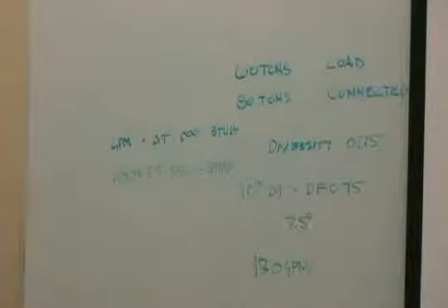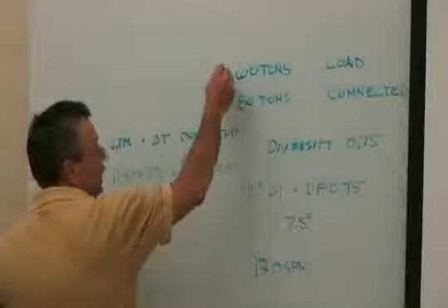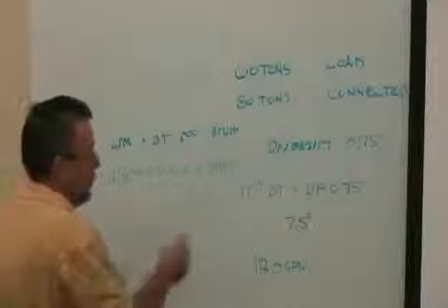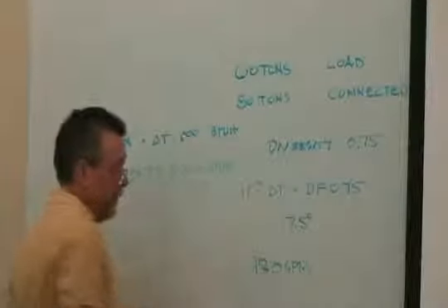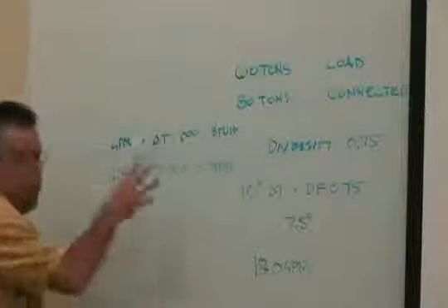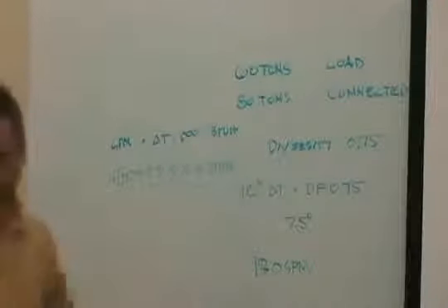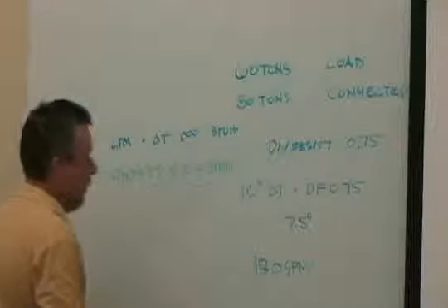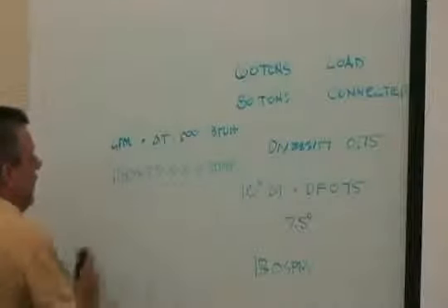You go through a similar process sizing the boiler using your heating load, your connected load of the heat pumps, times the diversity factor, times delta T, same thing, select the boiler. There's a lot more to it, and it takes a little more information than this to go through the process, but that's basically how the equipment is sized.